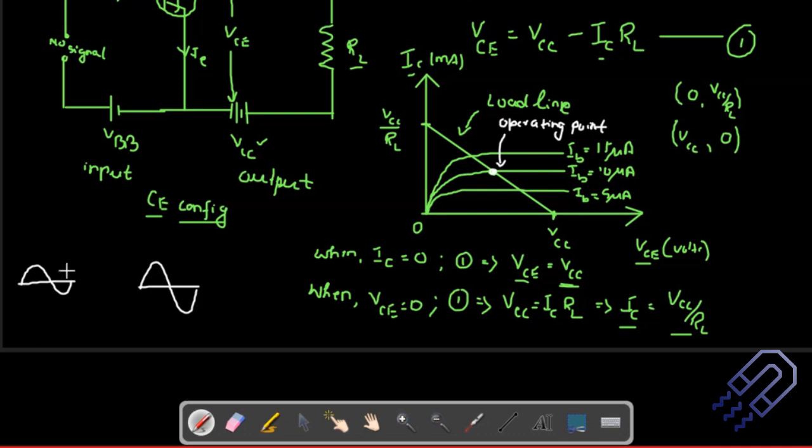The point here is that if this is smaller in amplitude and this is larger in amplitude, that means this has a larger energy. Where did it get that extra energy from? That extra energy is obtained from the biasing that we have, VBB, VCC. The energy that this biasing has cannot be infinite, so energy conservation still works.